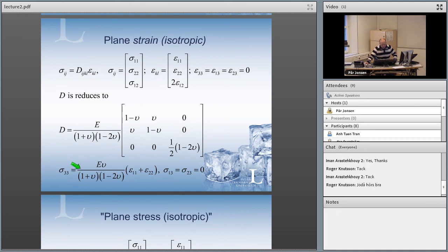Also, sometimes in the modeling, it's easier to simplify a model. For example, you use 1D, one dimension. You have just one position. Make the model, try to make it work for 1D. Then you change it to plane strain or plane stress, which is the next slide I will show you, before you go into a full 3D model. If you usually go straight into a full 3D model, you have a lot of problems. You also have problems with evaluating and calculating things. So I usually start with 1D and make it work there, and then I expand my model. It's much easier to do that.